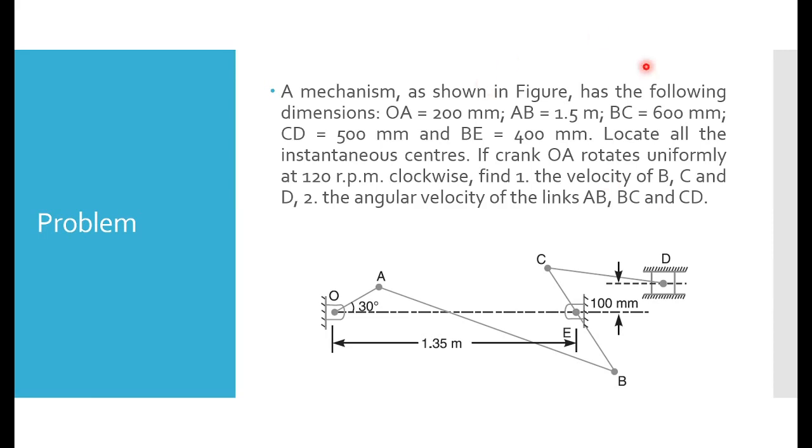So accordingly you have to draw. That is the first part I am telling. Then this is the next part. You have to draw again, because it is better advised to draw again for better understanding of the analysis. Solving a problem and locating all instantaneous centers are different. To locate all centers, we go through all the possible ways and locate all the centers. But in case of a problem, we need to locate only specific centers, so we should not locate any other centers. Then it will be helpful if you draw another space diagram. So first step is drawing the space diagram.